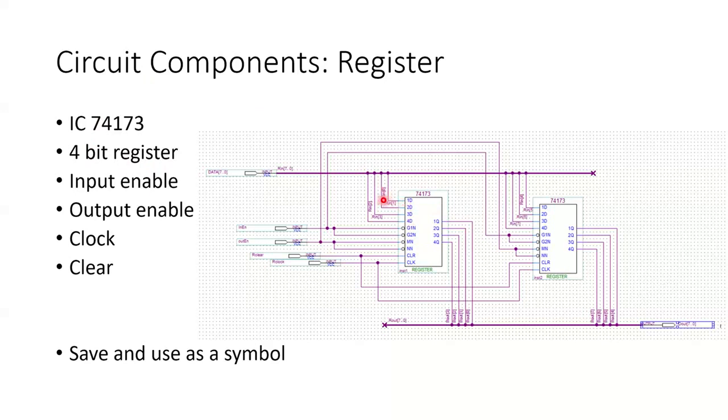So the 4 inputs coming into the IC are in 0, 1, 2, 3, and the rest of the 4 inputs, which are in 4, 5, 6, 7, are going to the other IC. And together we are creating an 8-bit register. So if you notice, the data pin 7..0 has 8 inputs, out of which the first 4 go into one IC and the later 4 go into the next IC.